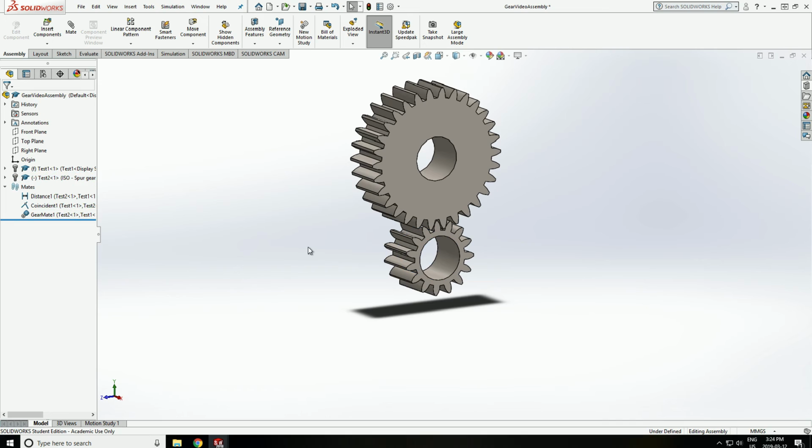And that's my way of creating gears in SolidWorks. It's probably the easiest to get started. There are other ways. You could of course create these gears from sketches and just do them manually. However, if you're going to work with a helical gear set or bevel gears, it becomes fairly difficult. So I would suggest go ahead, use the SolidWorks Toolbox.